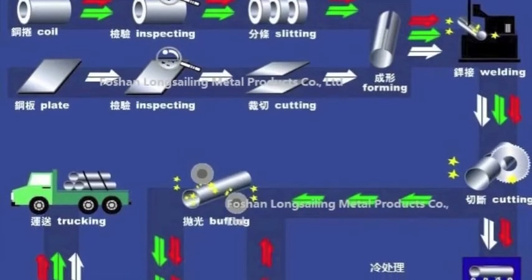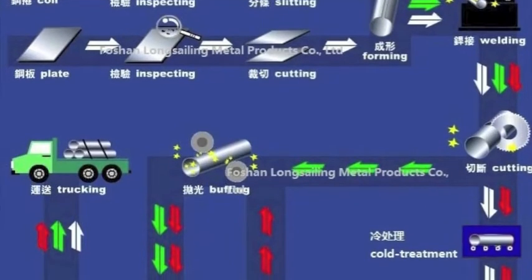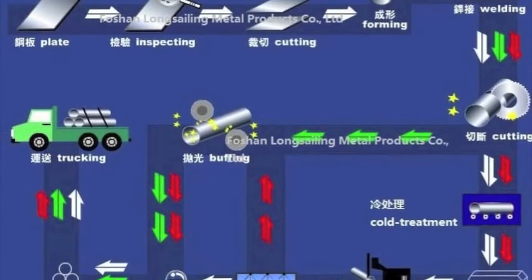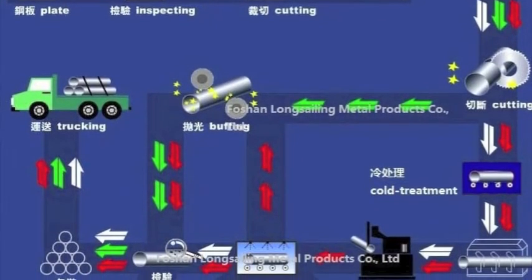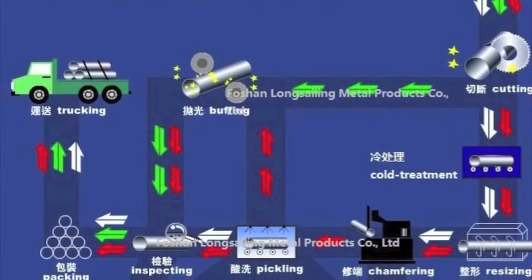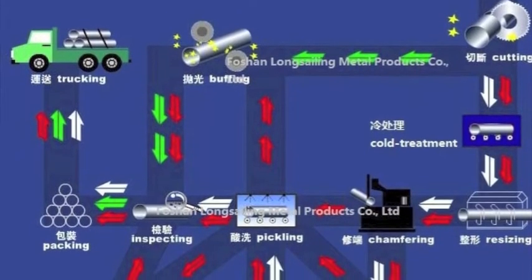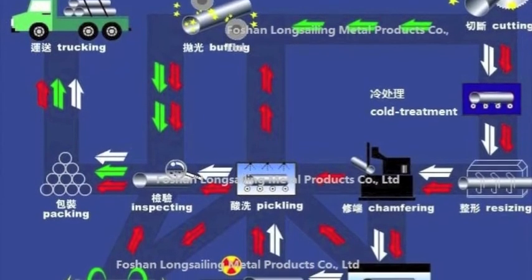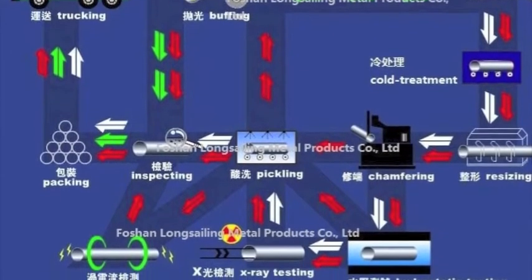They put a lot of scrap steel into a furnace alongside chrome or nickel alloys for adding strength and rust proofing. Electrodes heat it to the melting point, which is 1510 Celsius. Then they splash it with argon gas and oxygen. Then they can cut it into pieces.